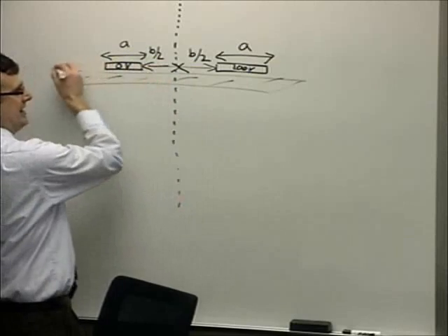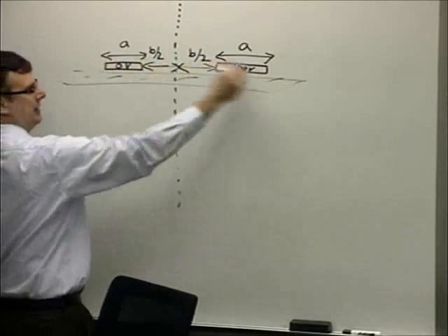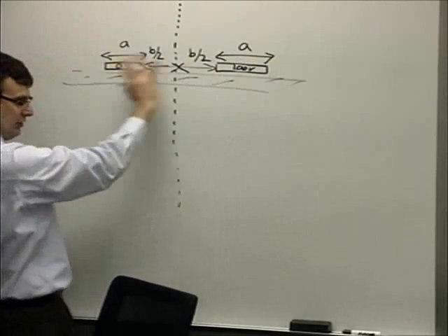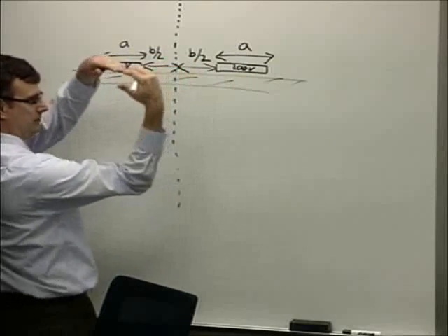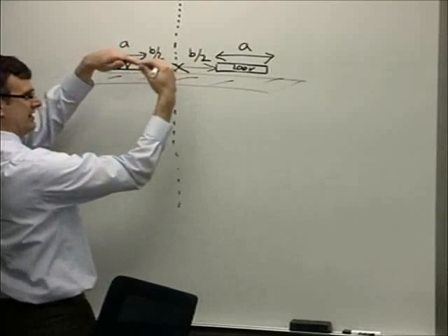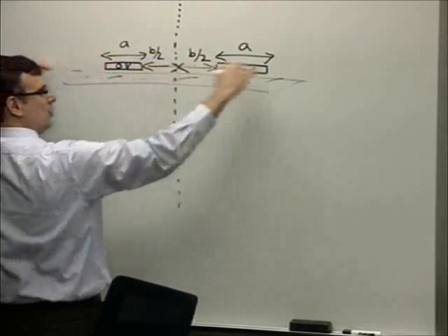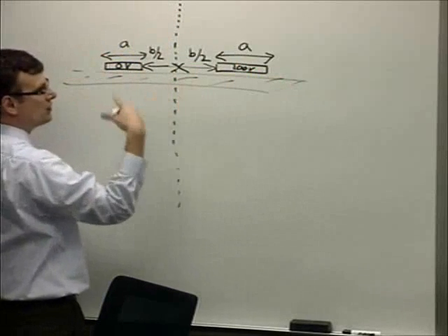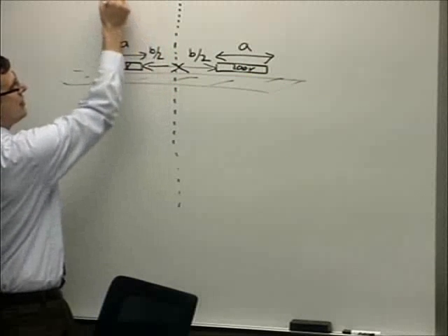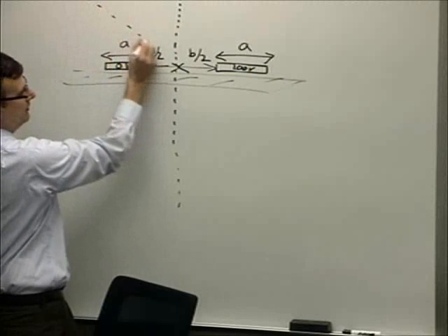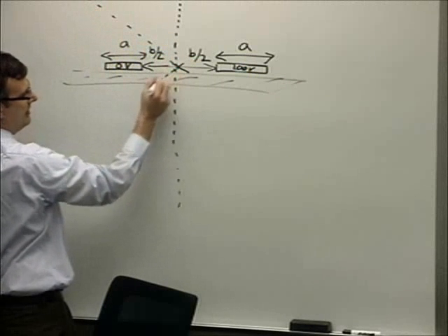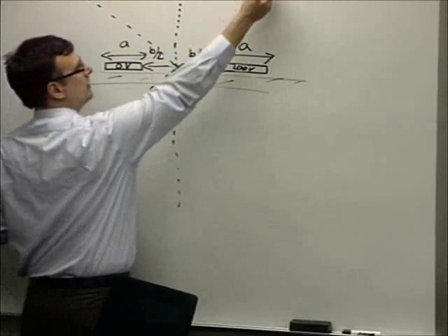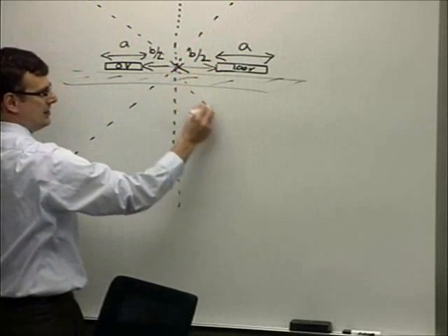If these were infinite, semi-infinite plates on a circuit board, and we're looking at the cross-section, keep in mind, they go up infinitely in this direction into the board and away from this line that I've drawn. If these are semi-infinite, then I know that there's going to be a 25-volt potential line there and there, a 25-volt potential line there and there.